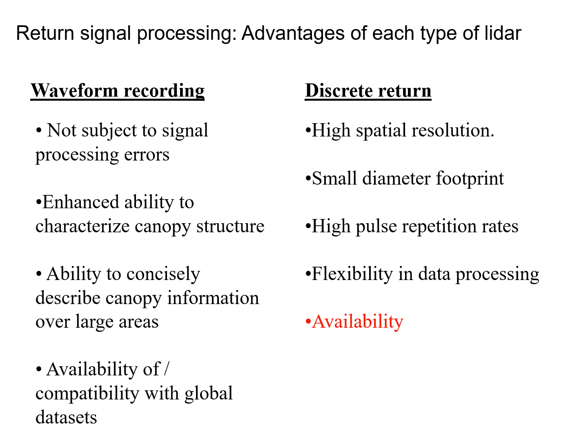Some of the differences between waveform recording and discrete return LiDAR. Waveform recording is not subject to signal processing errors. So in the discrete return case, you've got the receiver basically making decisions about what ranges are significant. And with waveform recording LiDAR, you just collect all the data.